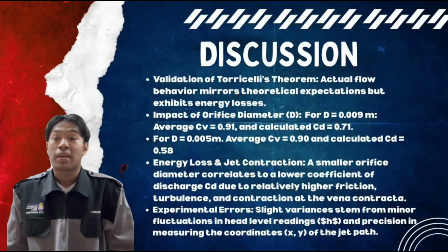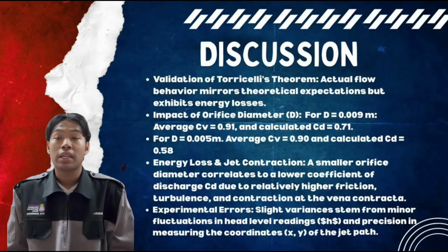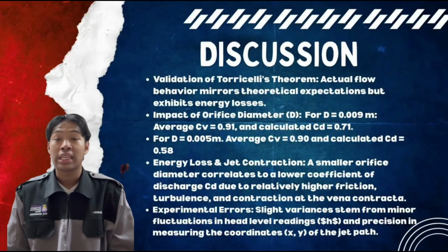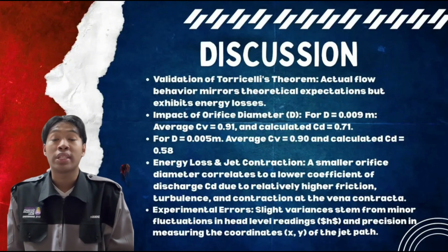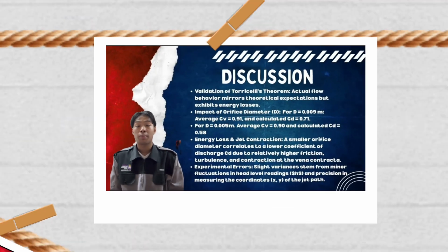Finally, minor experimental discrepancies are present. These primarily stem from parallax errors when reading the water head levels or slight manual errors when positioning the needles along the water jet trajectory. Overall, however, the direct relationship between CD, CV and CC strongly validates our hydraulic principles.